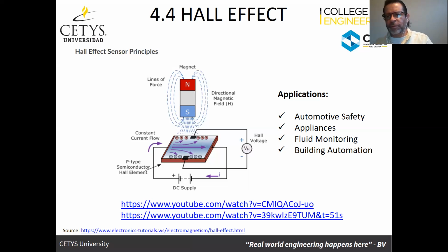It allows free movement for you, but the moment that you make a sudden movement or something pulls, it contracts, right? Well, if I put a Hall sensor or some configuration of a Hall sensor into the seatbelt mechanism, when there's a sudden movement, which is created by either the movement of the plaque through the magnetic field or the magnetic field close to the plaque, whenever a movement is generated, we're going to create a voltage here.